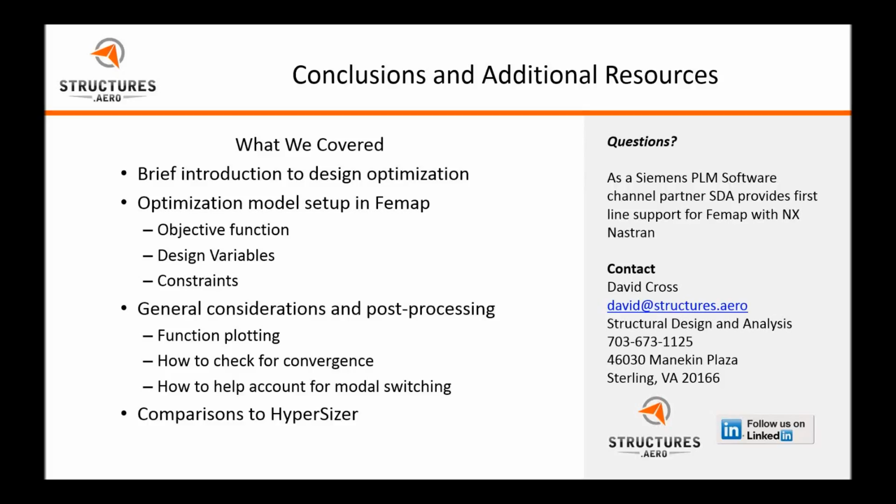Solution 200 does have the capability to define equations to several different responses. You can pull responses not from the property but from the element and then write equations. So you can definitely customize things like that. Femap doesn't support it, but there should be enough documentation in the user's manual to get you started there.